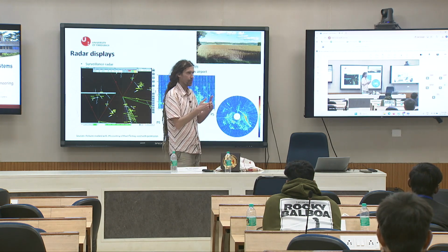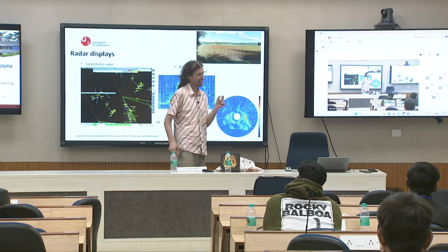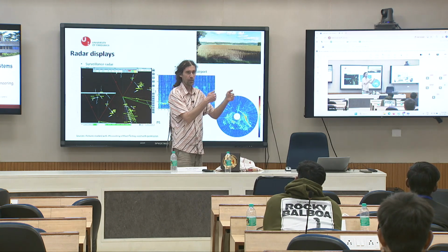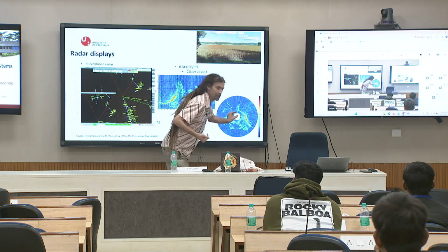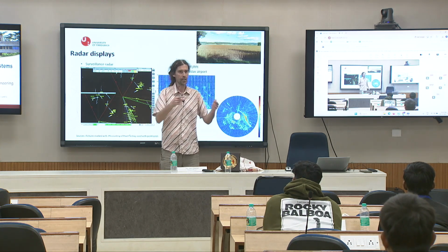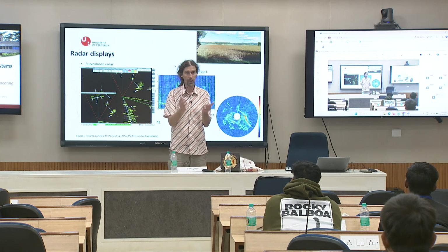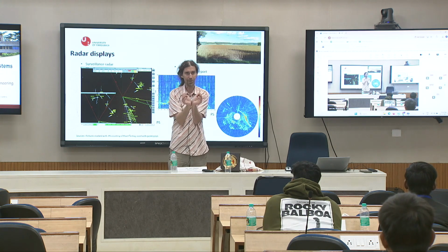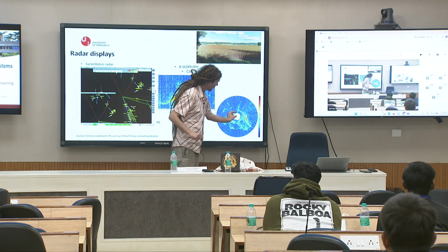Why? Because imagine, during transmission of your pulse, you can't receive, plus some extended time. Why? Because the reflection will be so strong that it will destroy your receiver. So this is the blind zone. It depends on many variables I will show you later. You can easily compute it, but you understand me. So radar generally has a blind zone.